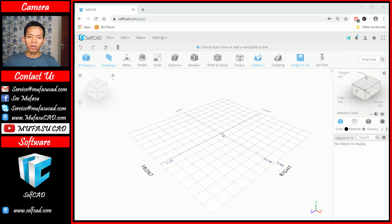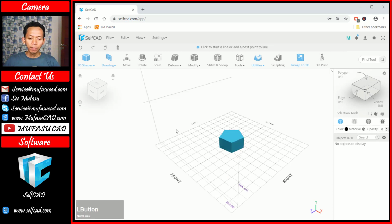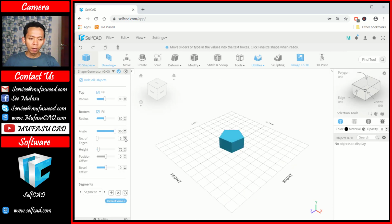Today we will learn how to create a 3D watchtower with basic commands. Okay, first I will create a new shape object. You can click here, Shape, and I will change the number of edges to 6. You can set the top radius and bottom radius to 80. You can click OK to apply.